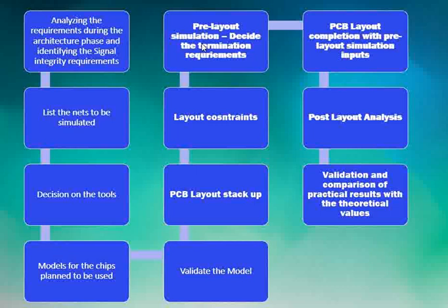So this is where all the termination related requirements, or the impedance related requirements, all the trace widths, all the spacing between the traces, all these can be decided in the pre-layout simulation. So pre-layout simulation is a very key aspect.